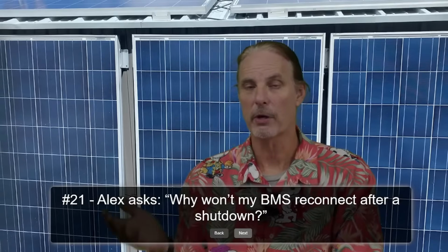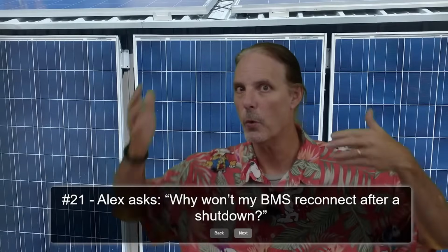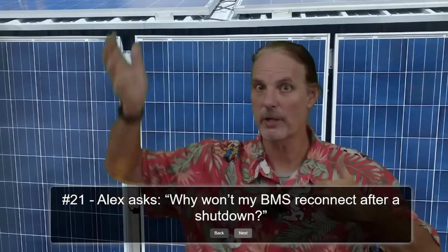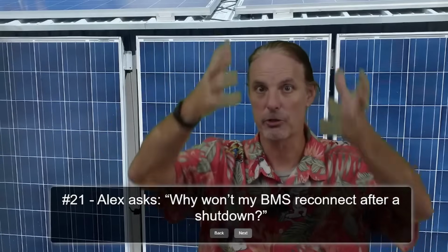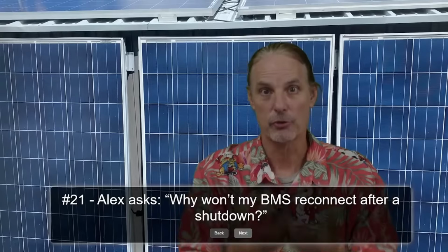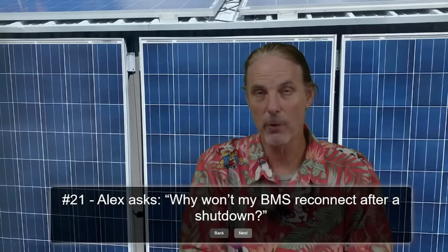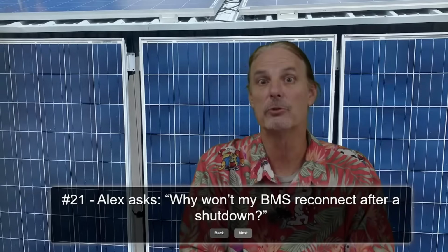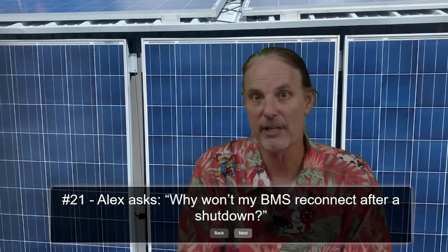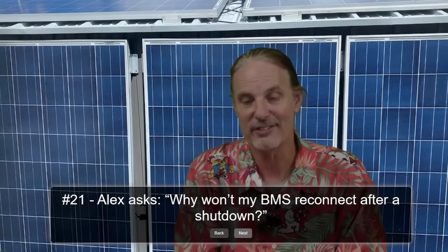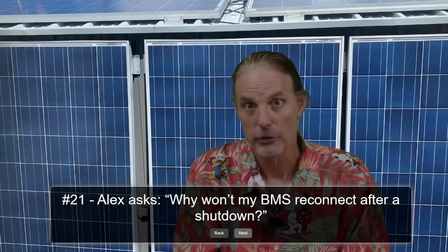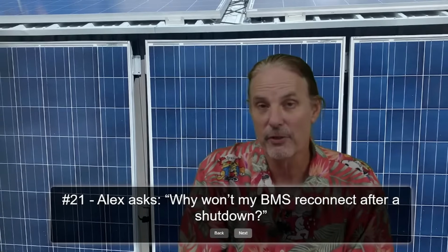The power can come from both the battery side or the solar side, and when the solar panels come up the next morning, they start to generate power, which turns on the charge controller, which then in turn can trickle charge enough power into the battery to enable it. It can also be a side effect of the battery itself that's shut down and is not allowing you to charge. So there are a lot of different things here.